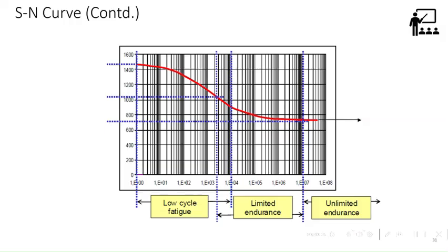Unlike the SN curve for 2000 series aluminum, which you can roughly consider the same, in composite, if the system is different, you might be using the same resin and same fiber, but with a different layer or orientation. That's it. You cannot use the same SN curve for that. You have to generate it every time, unless you use a standard resin and fiber for which open literature is available, which you can make use of.